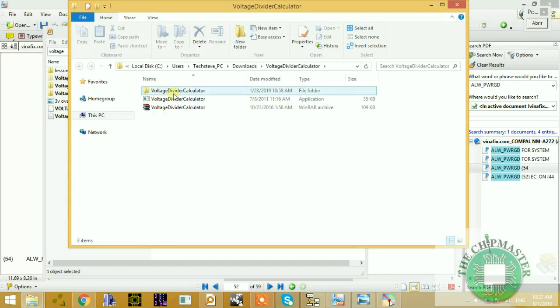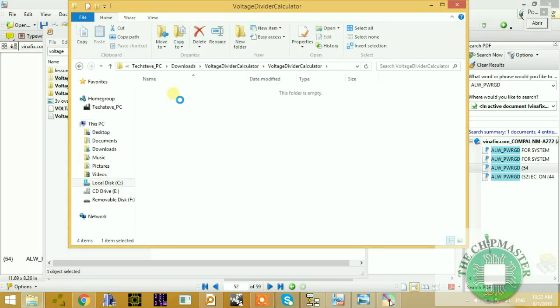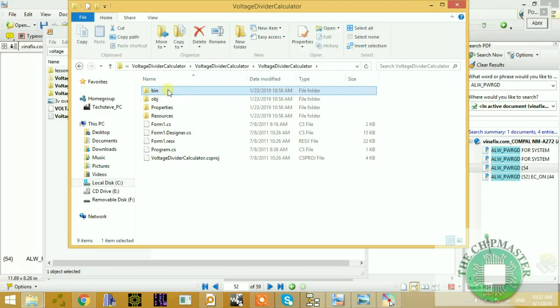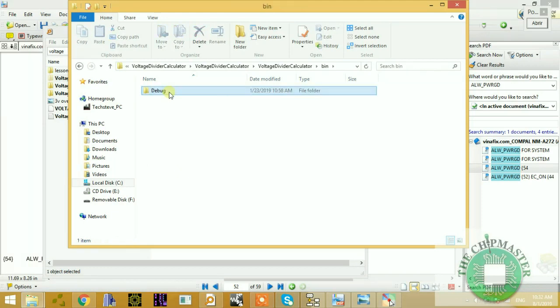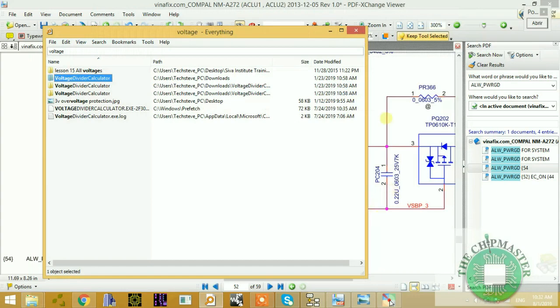Alright, it should be lower than 19 volts because it's a P channel MOSFET, so the voltage at the gate should be less than the voltage at the source. Okay, so the gate voltage should be lower than the source voltage.